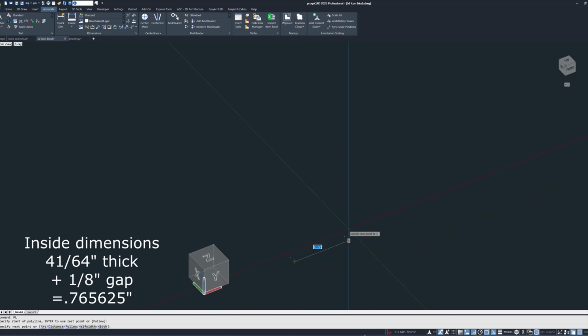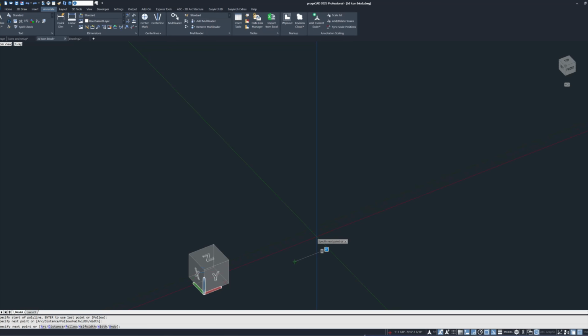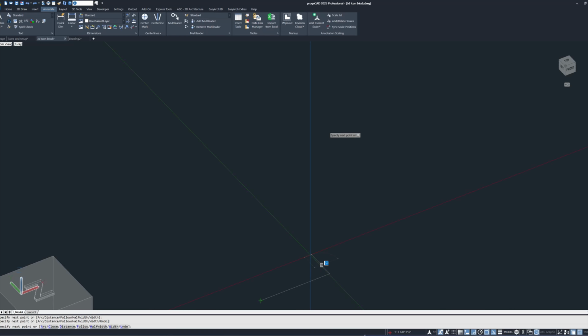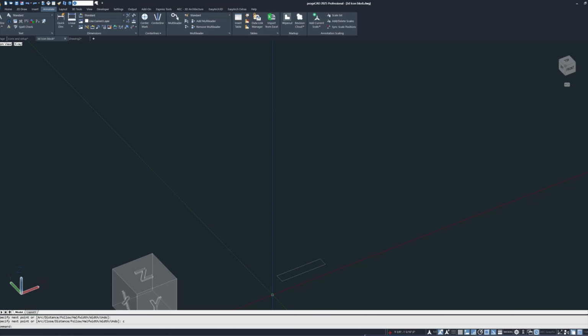Given the dimensions we determined earlier, we can enter the base of a starting box. We use polylines, a single-line element, to make it more understandable for this task. Make sure your orthographic axis lock is turned on so the lines will not go out of the X-Y axis. Enter the lengths of each side of the box as required. Once 3 lines have been formed, we can use the close command C to close the box. This box represents the interior of the box since that is what we measured. We added spacing inside the box to allow our phone to slide easily in and out of the box. We can now extrude this box to the height of the phone.